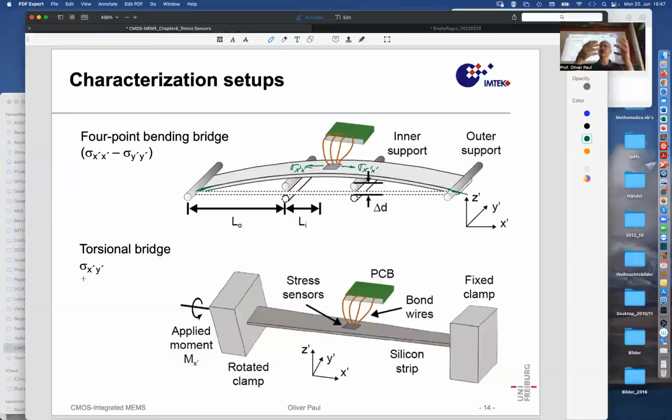That is the effect of a shear stress. So this is a method to load a material with pure shear stress on the surface. And that is what is happening also here. When you take such a stripe and then just rotate it mathematically correctly around its central axis, then the surface will experience a pure shear stress.